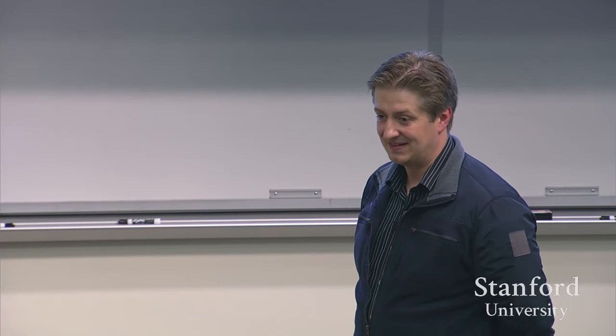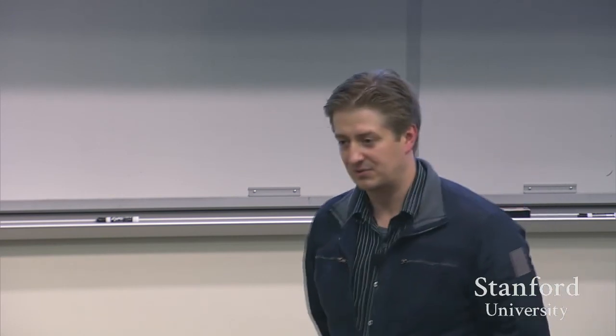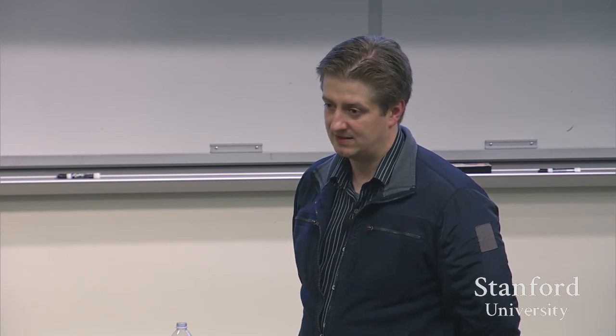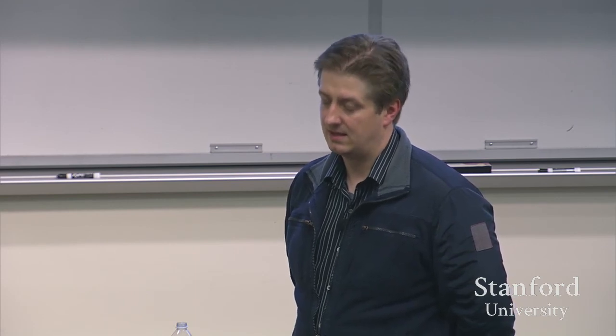Just as a rule of thumb, I know that about 5 years ago, no matter what machine you bought, you had about 4,000 dots per unit length of the machine. I see. What's the rule of thumb now? I'm not sure if I understand. Well, you had about 4096 pixels or voxels you could put across a device that was 3D printing something, whether it was a 4-inch device or an 8-inch device or a 2-foot device. No matter what it was, about 4,000.